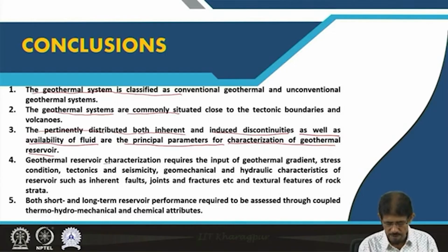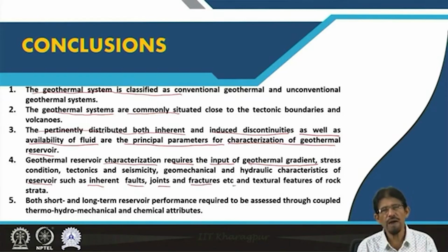And geothermal reservoir characterization requires the input of the geothermal gradient, stress, both magnitude and direction of stress present in the reservoir, then the tectonics and seismicity status of the reservoir or area where the reservoir is located, and then the geomechanical, thermomechanical and hydraulic characteristics of the reservoir such as inherent discontinuities like faults, joints and fractures, and the textural and petrological characteristics of rock strata or rocks are required for proper assessment of the geothermal reservoir.